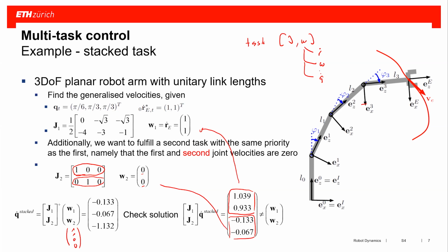So that's a good question. One relates to linear velocities, the other one relates to joint level velocities. So first of all, they can have completely different ranges and completely different units. I can give the velocity in radians per second or angles per hour or whatever. This is not defined here. And that means the least squares optimization, of course, figures out a different solution depending on the units that I'm taking there.